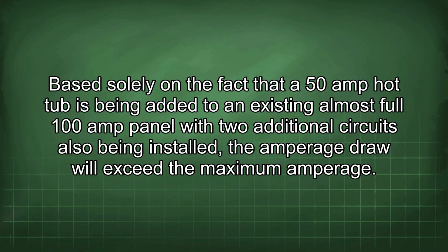Based solely on the fact that a 50 amp hot tub is being added to an existing almost full 100 amp panel, with 2 additional circuits also being installed, the amperage draw will exceed the maximum amperage.